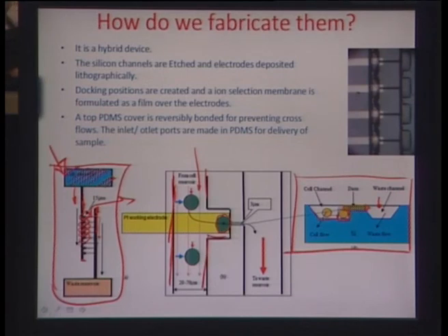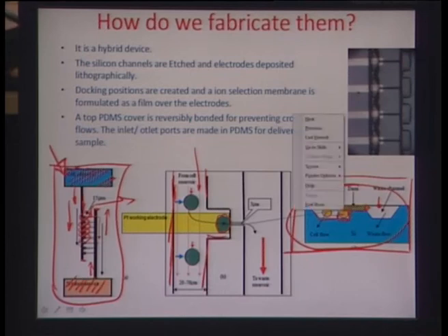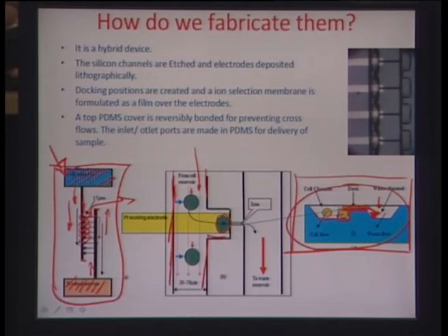So, if you see the waste side, you find out that the waste side also has a channel emanating from this waste reservoir, and it goes and stops or gets blocked all the way here, and there are connecting channels in between the main flow channel and the waste channel in this particular manner. Okay. So, the cell comes here, docks itself, and the solution which carries the cell is able to move from this particular dam area into the waste area. That way the fluidics is made continuous, the fluid flow is made continuous.